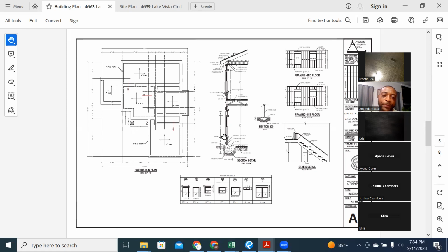And we use a term, which is not really a legal term. We call it a UFA. But when we looked at it for the NEC code, the National Electrical Code, it was actually a concrete encased ground, basically is what it is. So it's a ground, which is your rebar wire, which is encased in concrete.